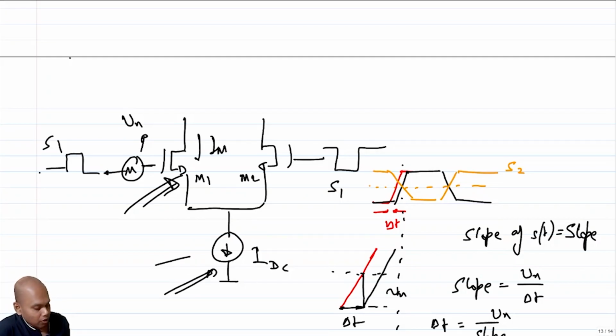But what is the downside to it? The downside is that if you increase the size of M1, M2, the capacitors associated with the gates of M1, M2 are large, and you want the swing at those big capacitors to be very fast, full rail to rail swing going very fast, which means you are going to have a lot of switching power. There will be inverters driving these gates, and you are going to burn a lot of switching power, which means you basically pay with efficiency, right?